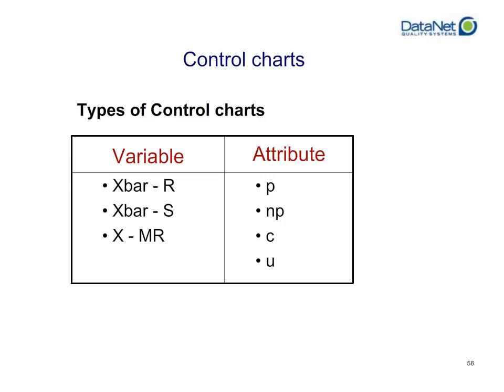Attribute charts are a completely different nature. There are no spec limits. Charts include things like the P chart, NP chart, C chart, and U chart. The most common one for defective units is a percent chart or a P chart that shows you the percentage good, and you can actually flip that and call it a Q chart. Then you can look at the percentage bad instead of the percentage good.